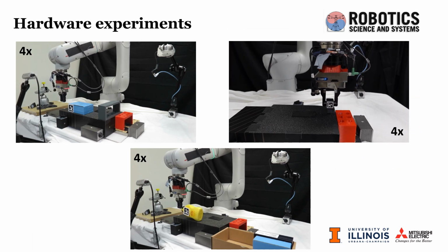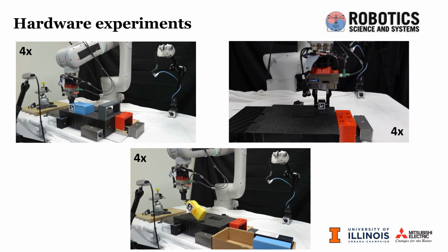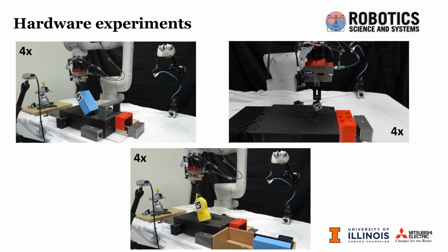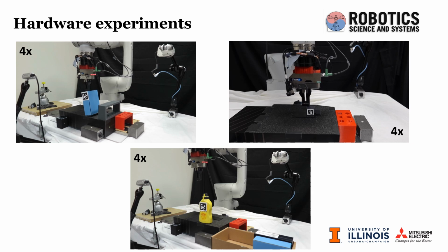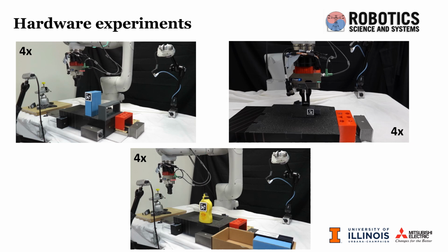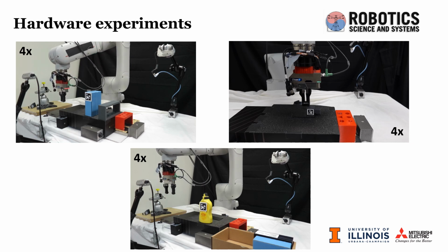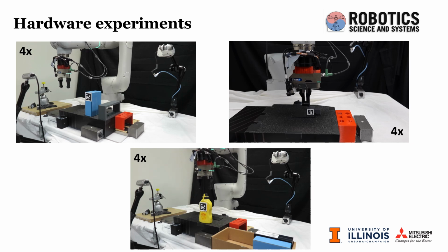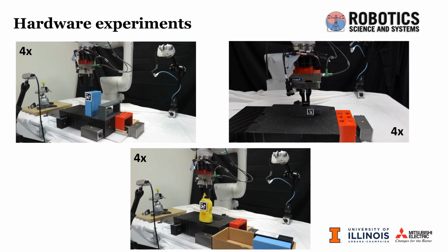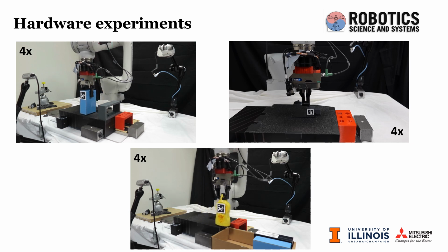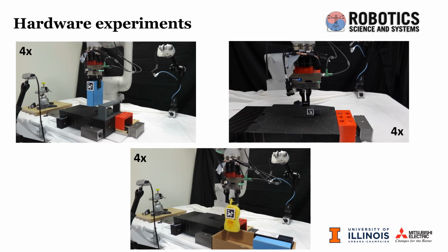Hardware experiments are performed to evaluate the planned trajectories. A Mitsubishi Electric Assisted Industrial Position Controlled Arm with a force torque sensor mounted at the wrist of the robot is used in the experiment. The default stiffness controller of the robot is used to execute the planned force trajectories. We use April tags to track the pose of the object, and when a single mode manipulation trajectory is completed and a new manipulator contact needs to be made, the object pose feedback is used to initialize the new contact.